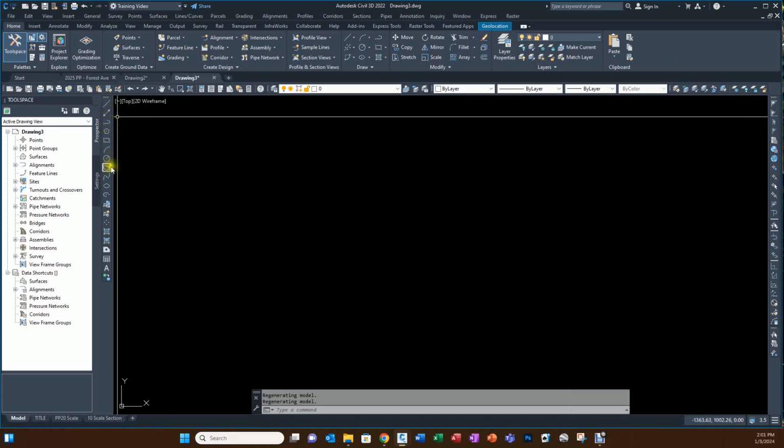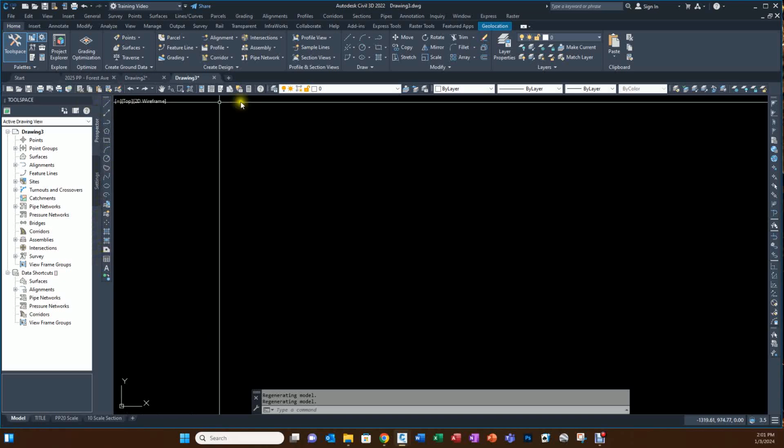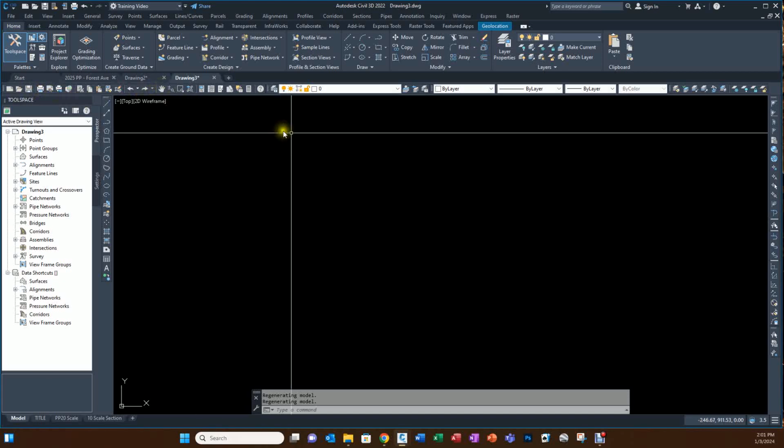Then beyond that, we have this button bar, different button bars for different tasks that we do. This is a drawing button bar. You can draw a line, a polyline, a hexagon or a polygon of some sort, or rectangle, things like that. This one here is your standard toolbar, and it has open, save, new, pan, all those kind of things.